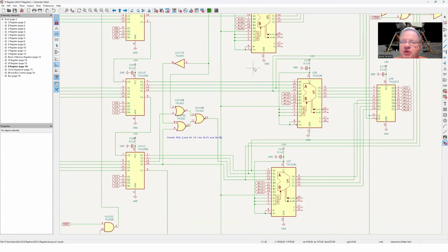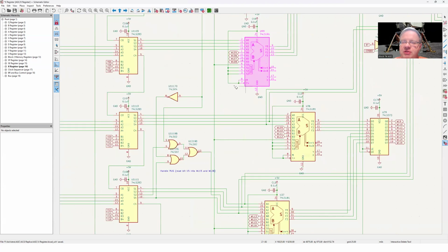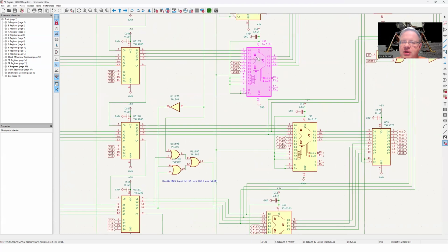If you want to look at the episode where we talked about the A register, we talk a little about the functionality. Again, one thing that's different is we only need to perform the logical OR. So S0, S1, S2, S3 is what we're telling the ALU through this decoder, what logical or mathematical instruction we want it to perform.